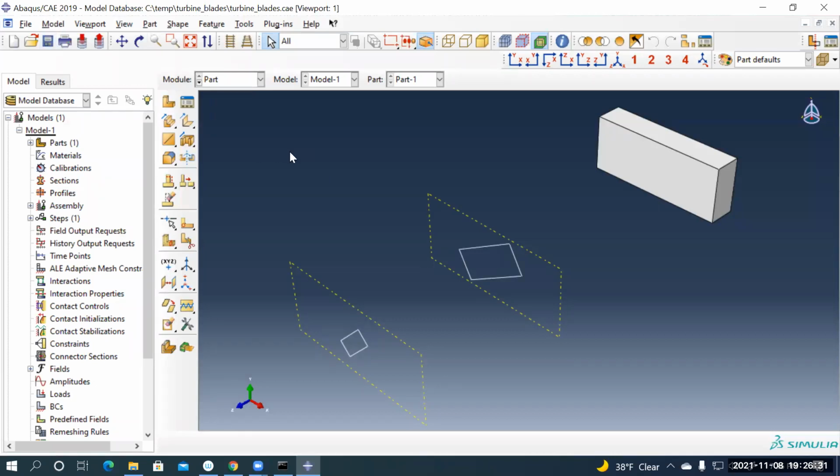So once you have, you need actually more than this. I just gave three locations. I gave the cross sections, and they are rotated also. So going to loft, go to shape, solid, loft.